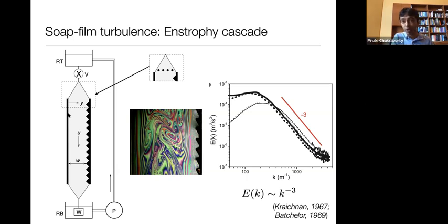And what you would find very close to the wall, and in fact, because it's a quasi 2D flow, you can really go close to the wall. I'm talking of the order of 10 microns. So you can find that there's going to be a region where the Reynolds stress is 0 or very, very small, and the whole flow is dominated by viscous stress. So that's the viscous sublayer region, so to speak. And because we have many data points over there, we can just take the slope of the velocity profile and compute what the friction is just by looking at the viscous stress. So using an LDV profile across the width of the channel, you can get the data rather straightforwardly. And these LDV experiments are fairly straightforward to do, and you can do them quite quickly.